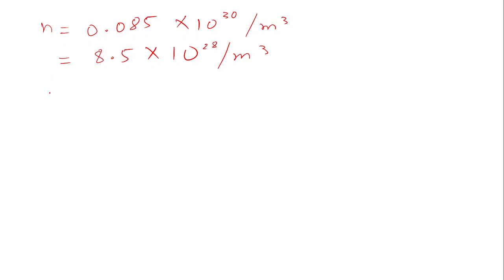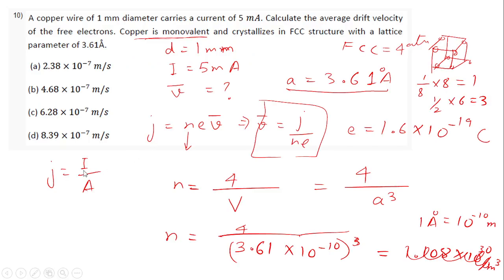After that comes current density, right? I told you we can calculate it, since current density is current per unit area, and the area will be pi r square because it's a wire, and a wire is like a cylinder. Current is flowing, charge is moving here, so the area is this cross section area. We call it cross section area because when we cut a wire, this is what we see.